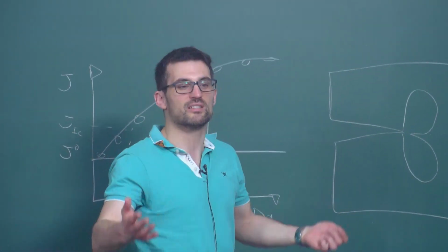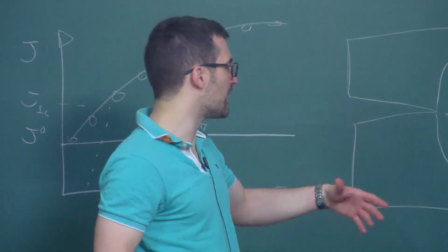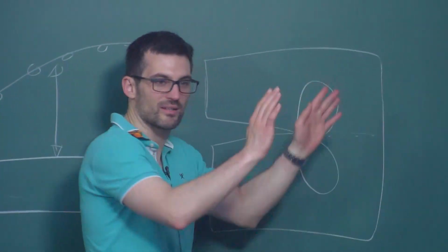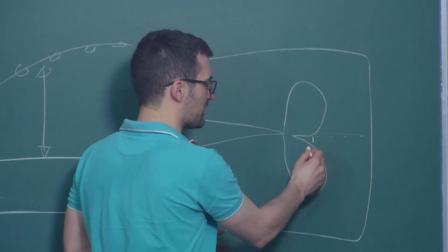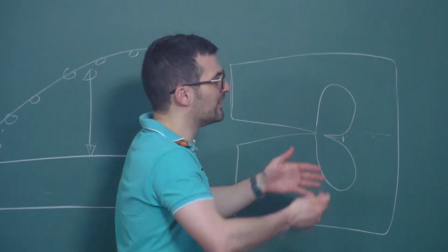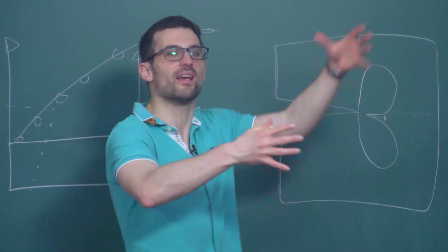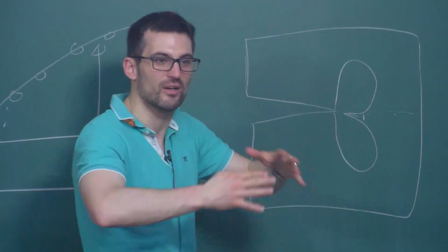When Irwin did these things before finite elements existed, and when people started doing finite elements, they realized that the Irwin plastic zone was more or less an approximation. In reality, it's a bit smaller if you think ahead of a crack. But in any case, everything scales proportionally. So it's an indication of how big your plastic zone is.